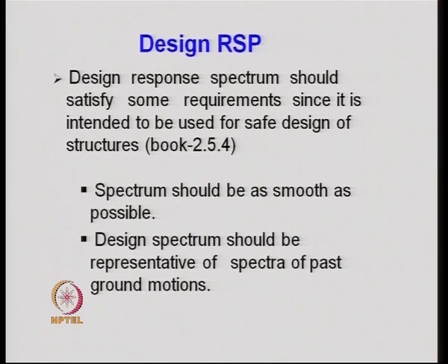However, the design response spectrum should satisfy some other requirements. For example, the spectrum should be as smooth as possible, and therefore idealizing the response spectrum by a series of straight lines is quite rational.